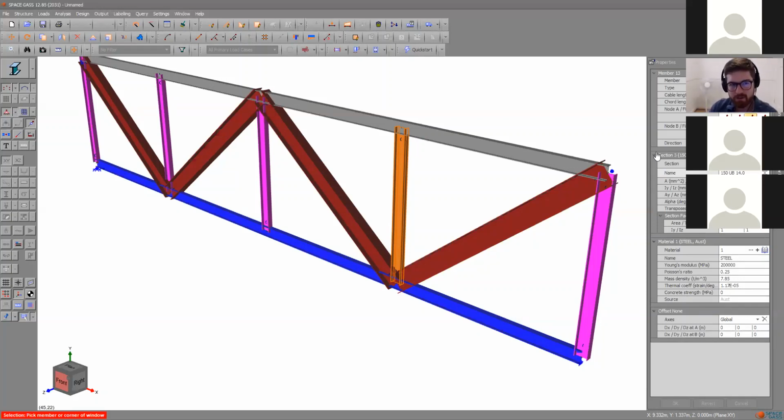There are other software tools which have similar functionality, a lot of finite element packages in particular, and you can actually run your entire model from Python, or you could run it from Excel, really, even if you wanted to. And then you can automatically build your model, analyze it, and then get your results back out without necessarily having to open this interface and put it in manually.